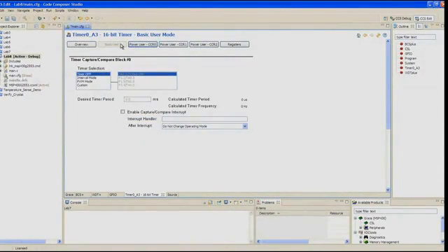In our application code, we're going to put the CPU into low power mode LPM3. After a 1 second delay, the CPU will run the ISR that turns on the LED. Our main code will wait long enough for us to see the LED, turn it off, and go back to sleep. So we need to make the following settings for the timer.